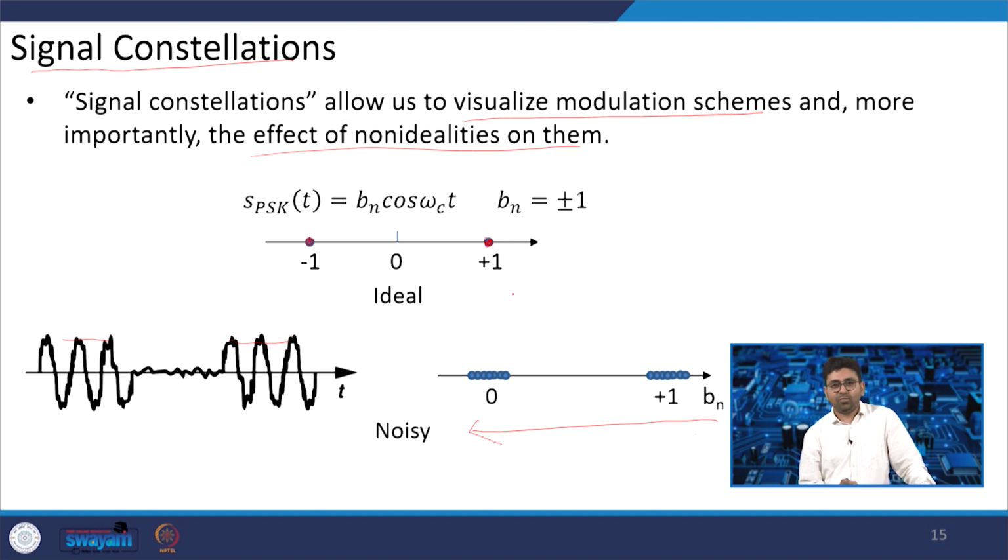But when we pass this signal through a noisy channel, which adds noise, the amplitude of the reconstructed signal will be different, at different 0 or 1 amplitudes, but near around that. So, when we try to detect the signal as 0 or 1, we need to put one threshold line in between, and this threshold line will tell us which side of the bits are 1 and which side are 0.